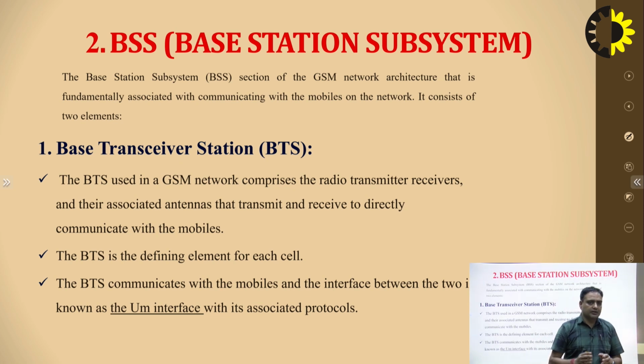The BTS defines the elements for each cell. Already I have discussed that each BTS has 2 or 3 cell IDs, and each cell ID has a unique ARFCN, absolute radio frequency channel number. On this particular frequency number, the user will communicate with another mobile subscriber.